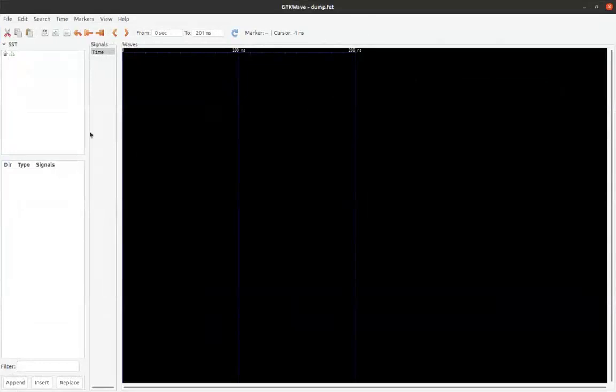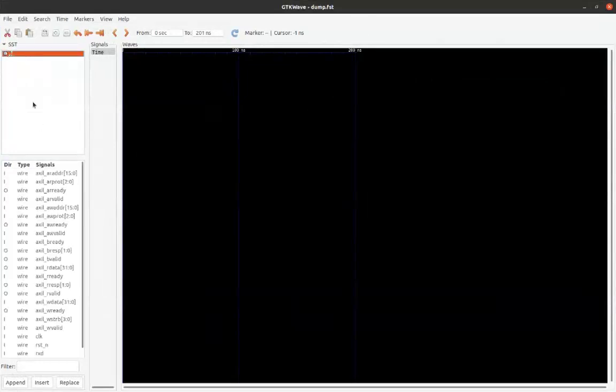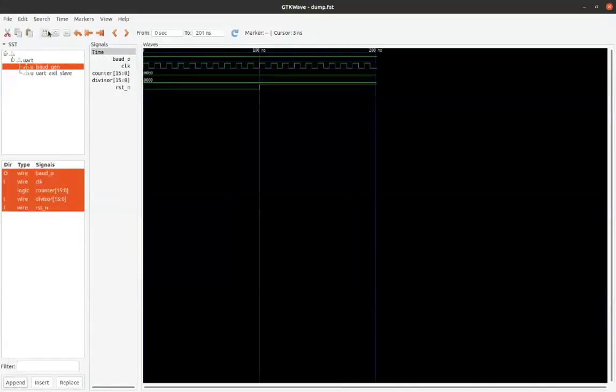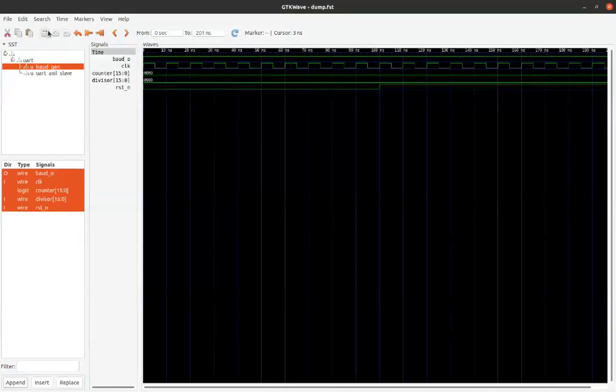Okay, so we have not done anything on AXI-Lite, so we can directly go to the baud gen module, where we have a very small set of signals. Let us see how it works. Okay, so this baud was high because this divisor signal is kept at 0 only, though I expect this to be set to 651. Let me check.